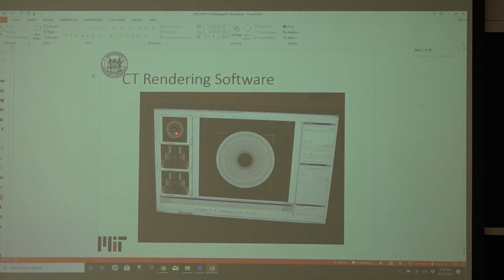You have a top down orientation, a basically side view, and a top down view. And this is where you can segment the sample and decide if you want to look at quarter thickness, half thickness, 3/4 thickness. You can do it much more easily with this equipment than trying to do it with a manual technique.